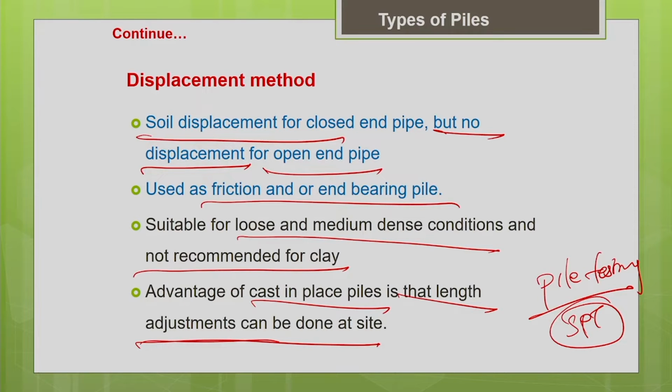In addition to this, there is also another method where they use bentonite slurry for the piling. What they do is use the bentonite slurry to act like a formwork to the soil. So, this will be more cost effective when compared to steel formwork. Where the soil has a poor bearing capacity, they use this bentonite slurry, so that it will help to stabilize the soil and prevent the collapse of the soil.